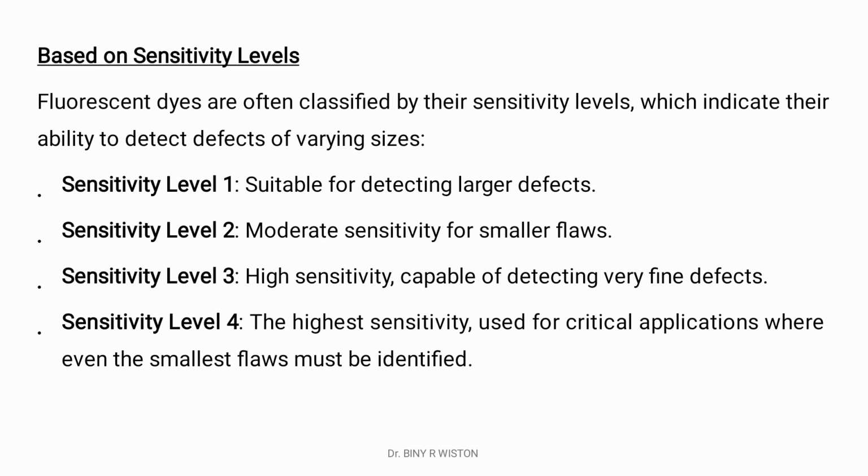Based on the sensitivity levels, fluorescent dyes are often classified, which indicates their ability to detect defects of various sizes. Sensitivity level 1 is suitable for detecting large defects.